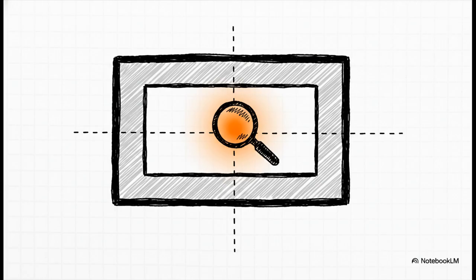Take a look at this hollow rectangle. A perfectly centered hole was cut out of it. Because the cut was concentric, the shape is still perfectly symmetrical both horizontally and vertically. And where's the centroid? It's still at the intersection of those two axes of symmetry. Even though that point is now in thin air, it is still the true point of geometric balance for all the material around it.